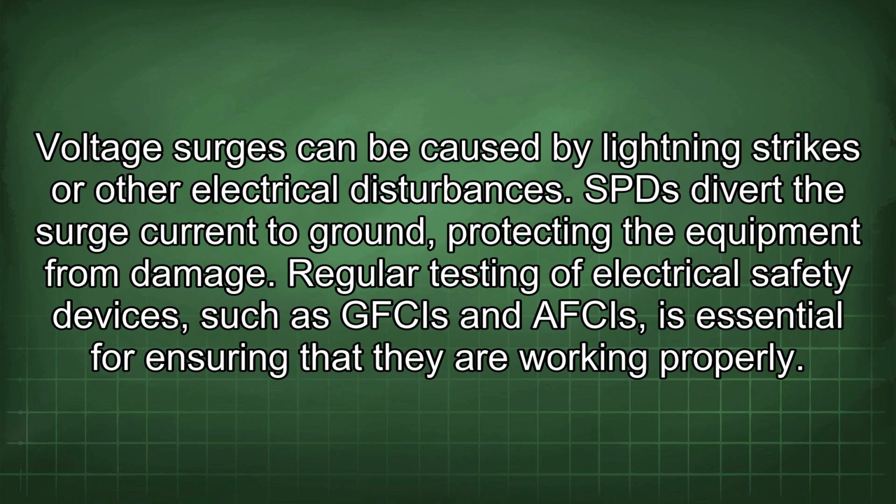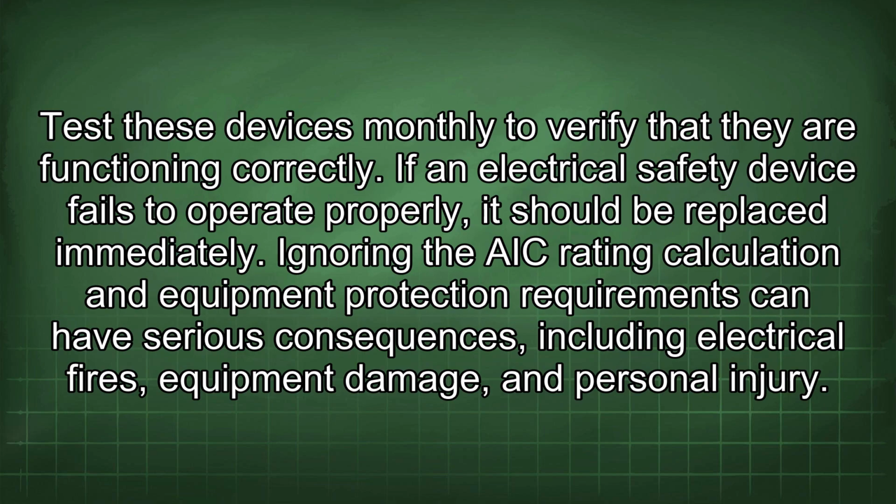Regular testing of electrical safety devices, such as GFCIs and AFCIs, is essential for ensuring that they are working properly. Test these devices monthly to verify that they are functioning correctly. If an electrical safety device fails to operate properly, it should be replaced immediately.